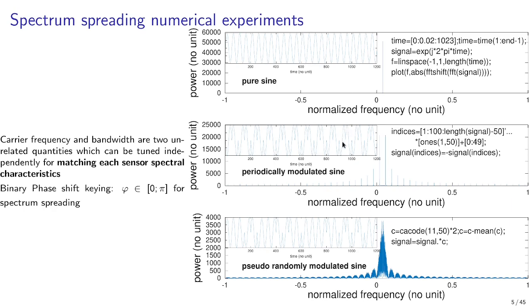If we want to introduce some sort of timing information, we might flip, BPSK encode, 1 out of 2 periods. By doing this, we can identify even periods or odd periods as encoded with 0 or pi phase. The timing capability is a bit better. We see some additional spectral components appearing in the spectrum, but it is not very efficient because only 1 out of 2